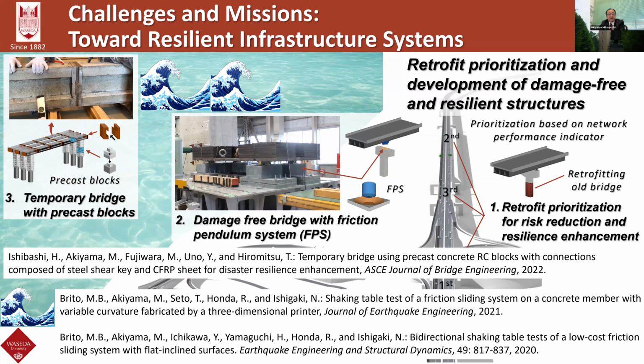So now my team is developing a temporary bridge using precast reinforced concrete blocks with the connections composed of steel and concrete shear keys. The picture shows steel shear key and carbon fiber reinforced polymer sheet or a coupler of longitudinal rebars.